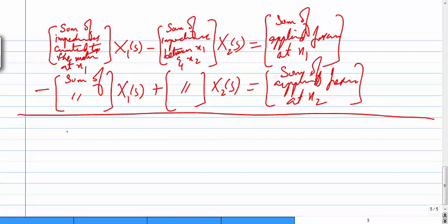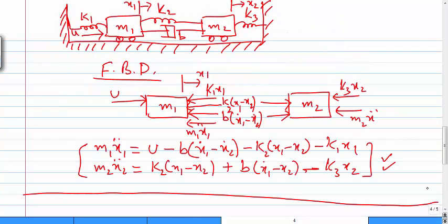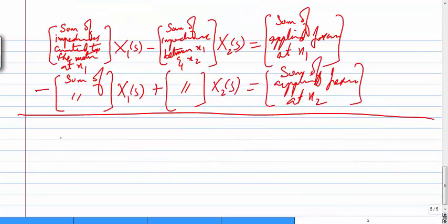So the movement with respect to x1, if you look here, is due to k1, k2 and damper. So if I say k1 plus k2 plus, for damper we have to put s, because this is not with the x only, this is with the velocity.